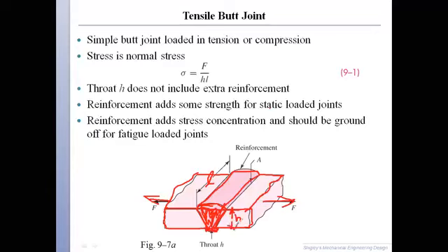Okay. So what would be the stress? Look, what will be the area of the weldment? A is equal to H times L, because it has thickness H and the length is L. So we can calculate the normal stress on this weldment, which will be F over HL.